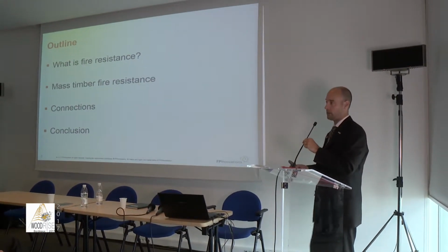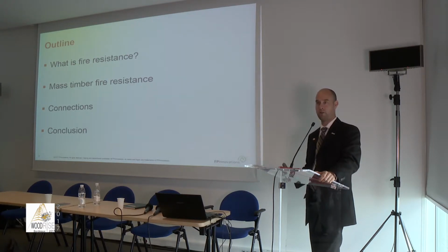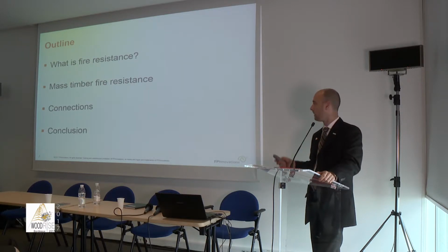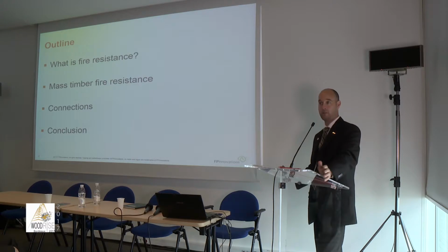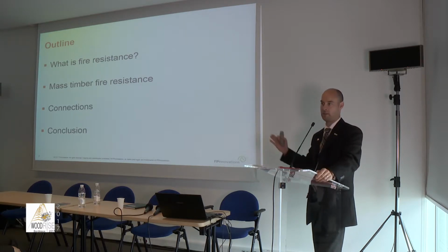And then we'll go through how to assign fire resistance to mass timber elements. I'm going to show you as well some results from Canadian fire tests that we conducted over the years. Some guidance on connections. Unfortunately, connections are still today one area that is missing some guidance on how to design for fire resistance. There is plenty of research for, I would say, short durations, so up to 45 minutes to 60 minutes in some cases, but otherwise for 90 minutes and 2 hours, there is very little test data available for now.